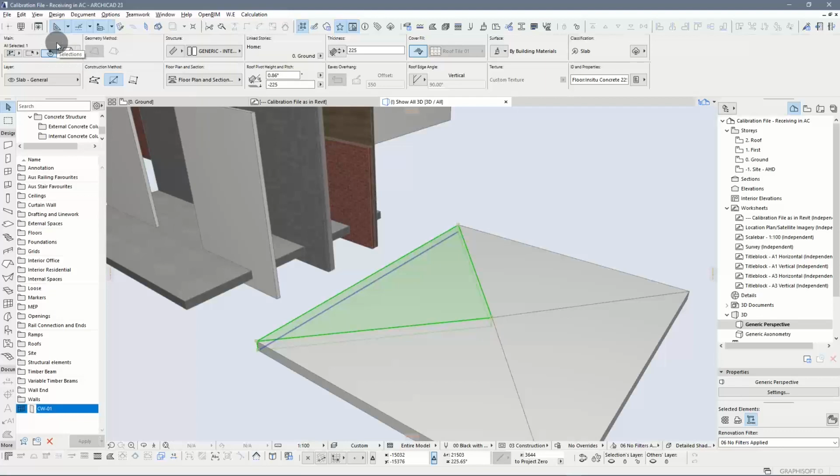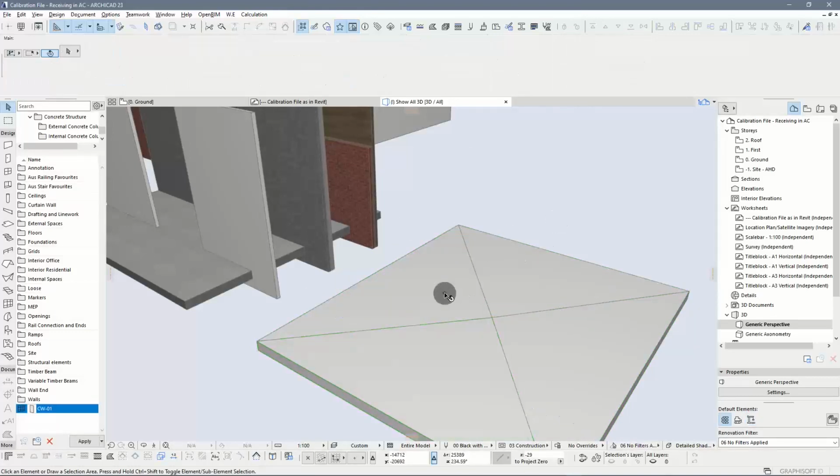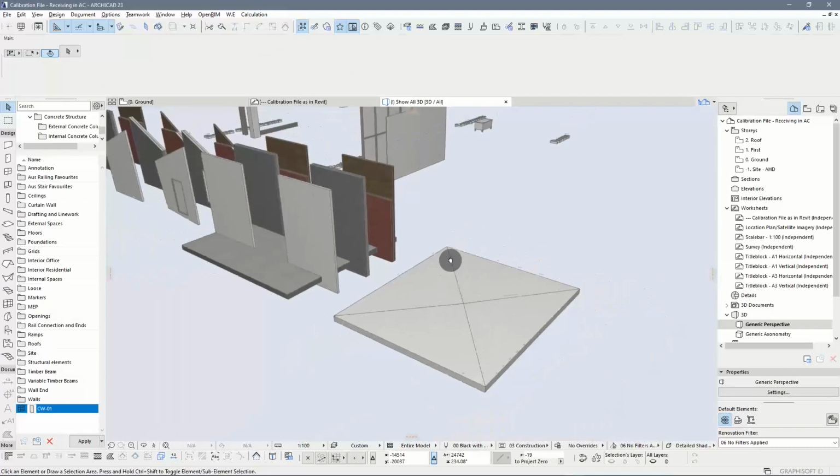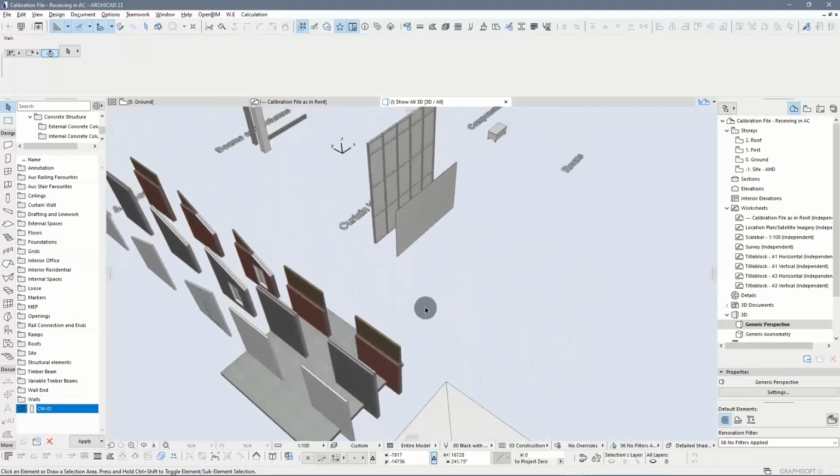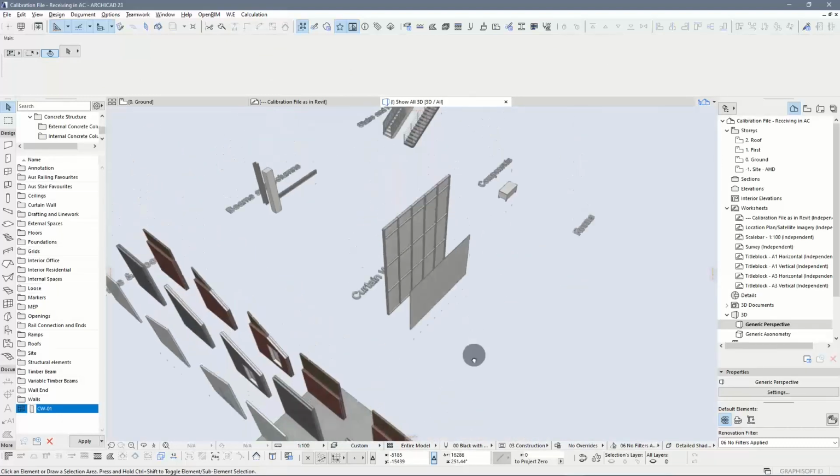But note the following, which is a pretty smart thing to do for Archicad. It will create that with the roof tool, but it will actually understand it and classify that as a slab, as it should be, right? So you get actually the individual slab just built out of the different parts. So that's how that will be translated, but that will be better than a simple B-rep like a morph and so on.